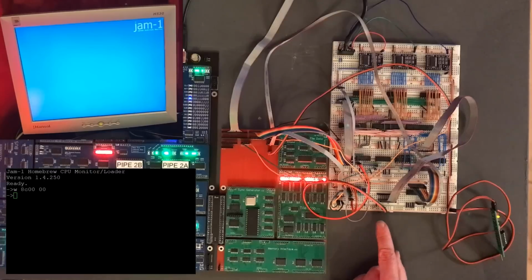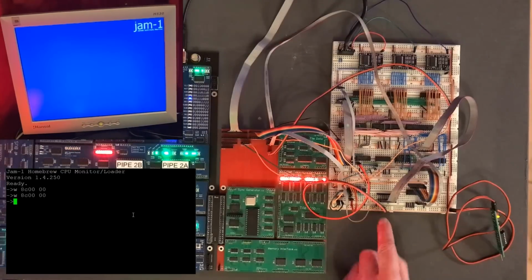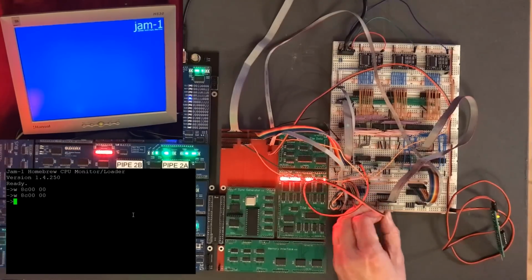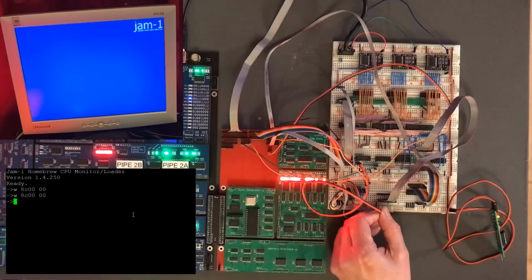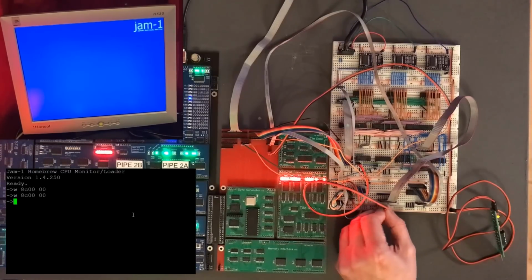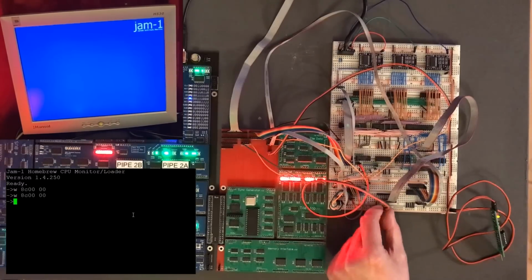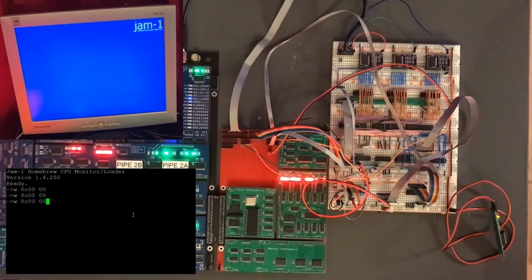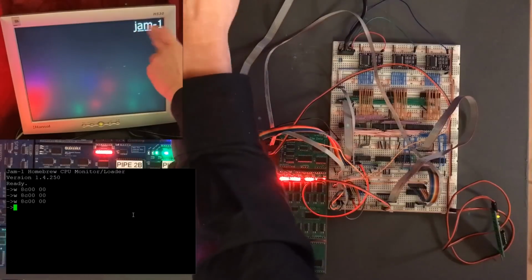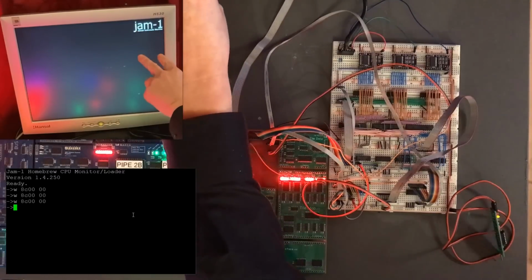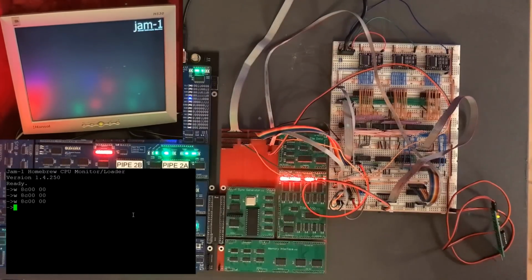So now that would be the second line is set high by the power line there. Doesn't actually matter what address we put in there. So that's binary 0, 0, then 0, 1, and now by turning it round, that's 1, 0. So I'm just hardwiring these address lines into the ground and power rail. So if that's consistent with what we're seeing, this will now mean that blue goes to 0. So it looks a lot more correct. This isn't quite right because whatever's happening to the address lines there isn't entirely consistent.